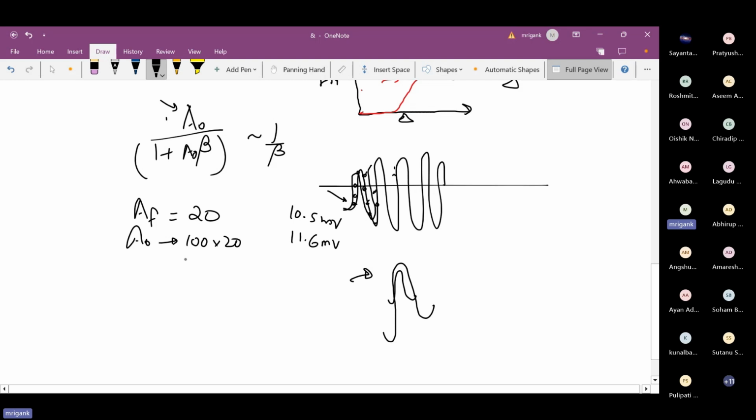Okay, so in LTspice, I'm not very sure whether you can. In Cadence, there is a way to bring in the outside data. Like the serial data is very much available. You can download that data and feed it in the Cadence. In LTspice, you have to check. You can always generate this data artificially also. If you just have a superimposition of some sine waves, you can generate some random data, and with that also you can work.